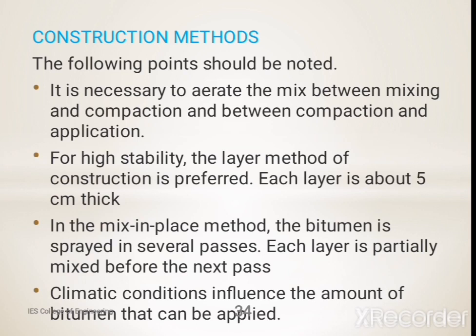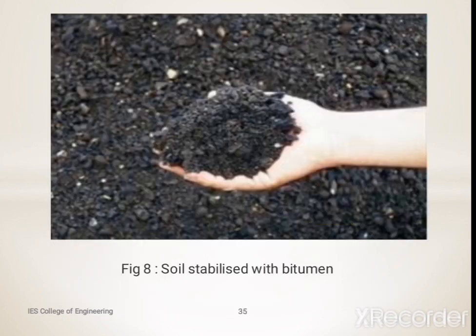In the mix-in-place method, the bitumen is sprayed in several passes. Each layer is partially mixed before the next pass. Climatic conditions influence the amount of bitumen that can be applied. The figure shows the soil stabilized with bitumen.